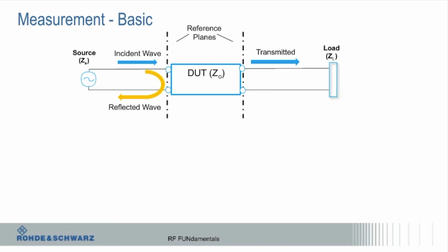And incidentally, my number one thing I support is VNAs, so I like to talk about VNAs. All this stuff where you see reference planes, I'll talk ad nauseam about this, so bear with me. After you do a calibration with a VNA, you're really establishing this reference plane. It's one of the cooler things about a VNA: with most instruments, you don't get to pick where you measure. The front panel of that device is really your measurement reference plane. You can add losses and things like that to it, but it's not really designed to automatically figure that out for you. That's what, to me, is really cool about a VNA. Okay, I'm a nerd, so bear with me.